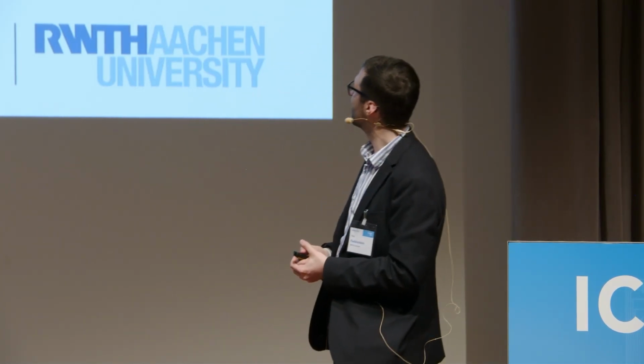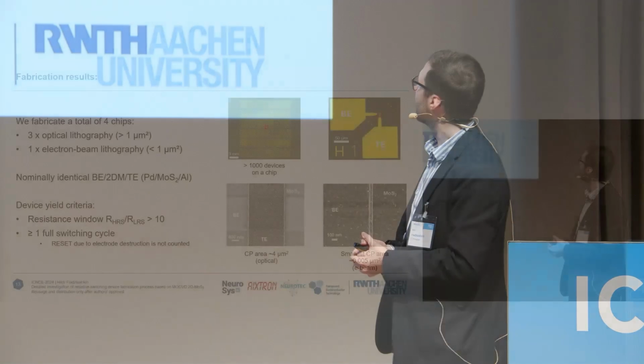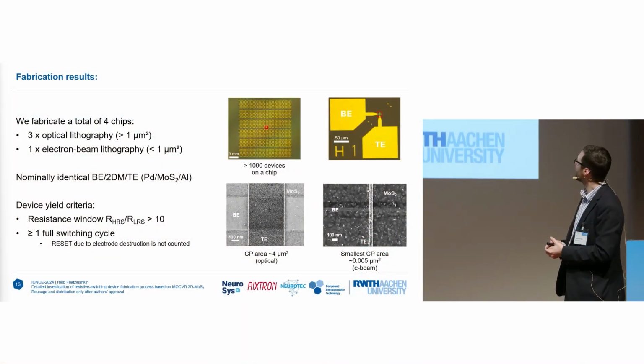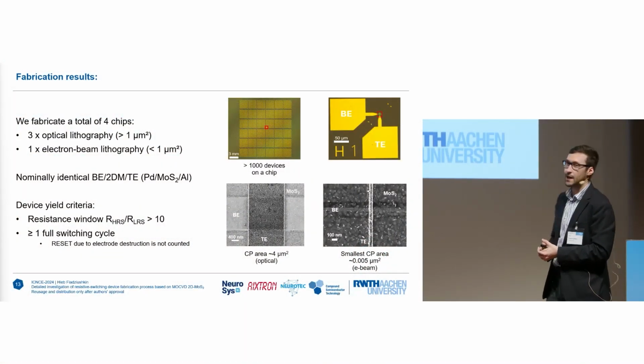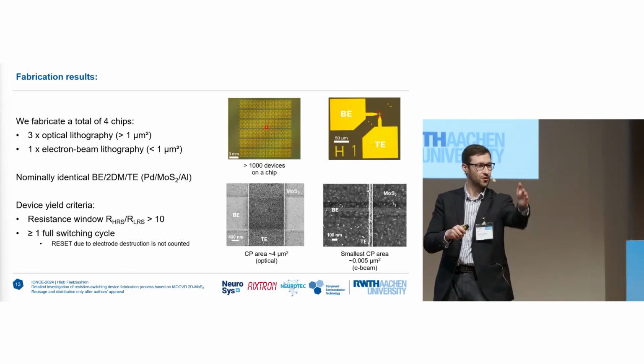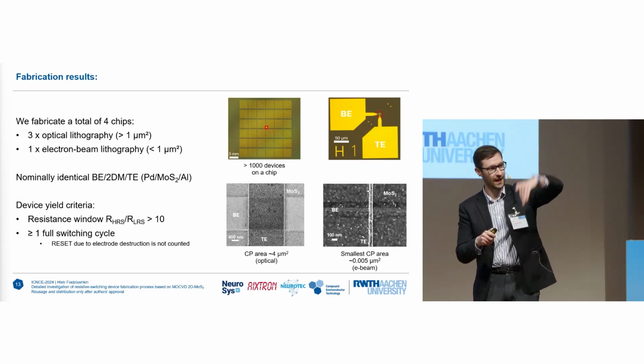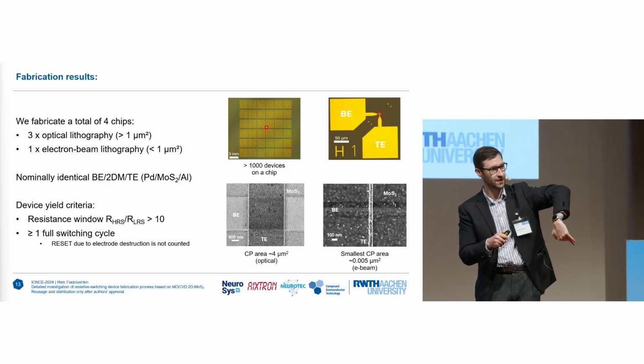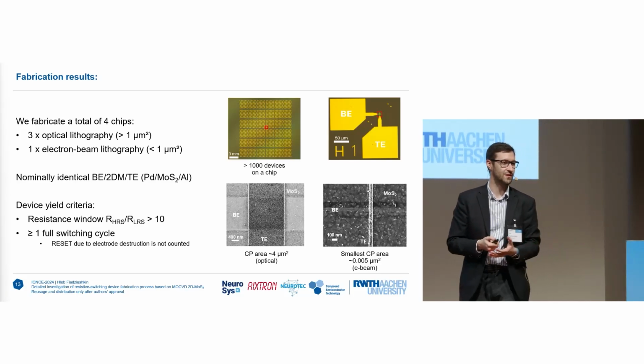The second question is about the images. It seems that at the interfaces you have some much lighter edges. Is that some artifact? It's just from the SEM. When you're doing electron microscopy, from the edges, from the side walls, you get slightly different signals because the incoming electrons get reflected, and it's just an image artifact.